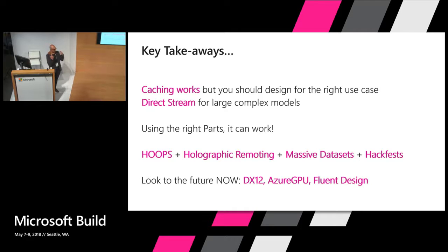For that use case, we don't actually need to use streaming, because if you think about just a 1 week or 2 week look ahead of geometry, it actually loads into the device. For that example, we used Vuforia image targets, and then just did a model alignment, 2-point, basically an origin point and rotation, and then the model loads up.